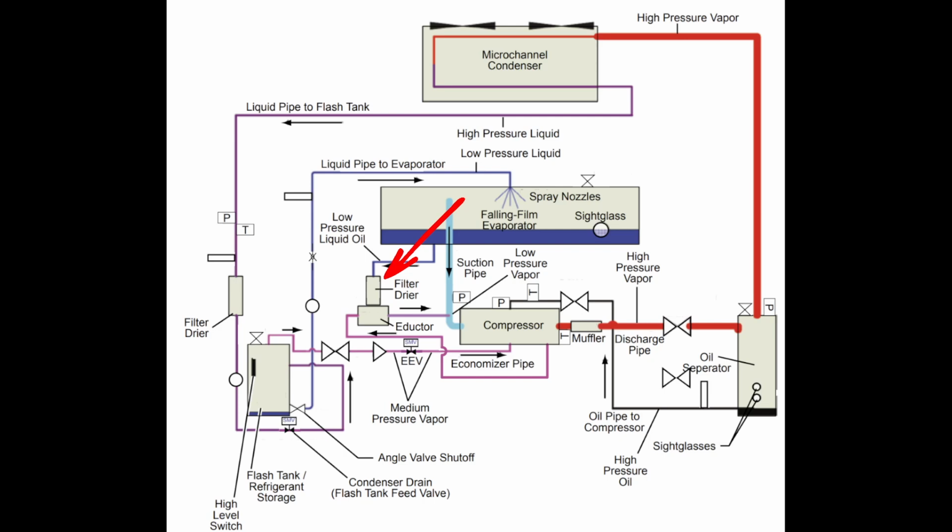In terms of getting into the evaporator, yes, you could have additional debris, whether it be some dirt from somebody opening up the system to work on it, or metal shavings from a pipe, or whatever happens. That material could be floating in that refrigerant and could get drawn into the line. So a filter dryer there will help account for any moisture in the system, but it's also a literal filter for heavy material. Yes, that would be one of the functions it could serve.